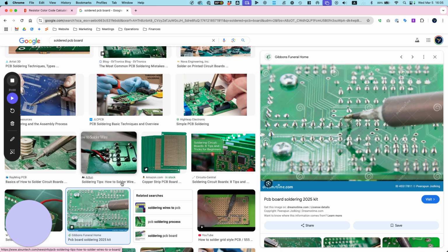Okay, so when I tell all my drone customers, if you're not going to use your drone batteries for more than a week, discharge or charge it up, depending on what state you're in, to like 60-ish%, okay? This is just for the longevity of the battery. It's not like it's going to blow up or anything like I said previously. It's just that if you want your batteries to last longer, you want to target that 60%.